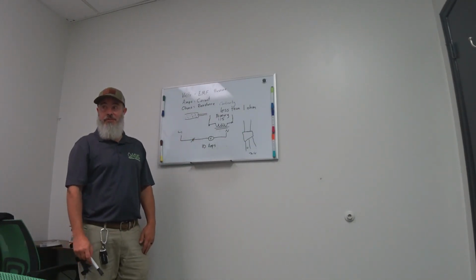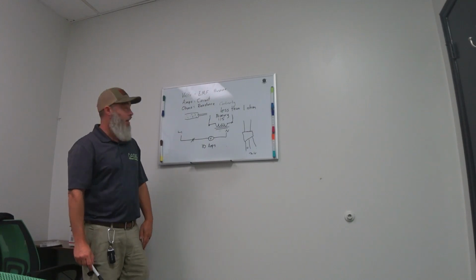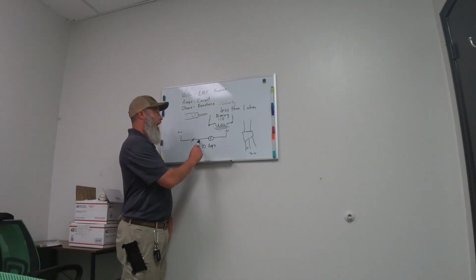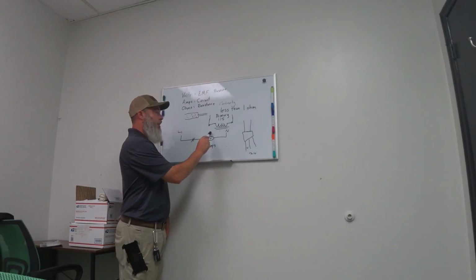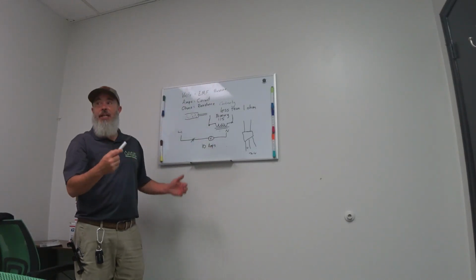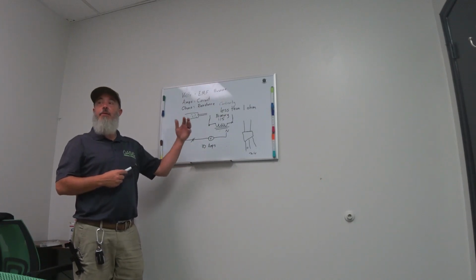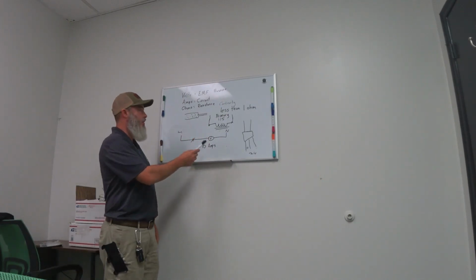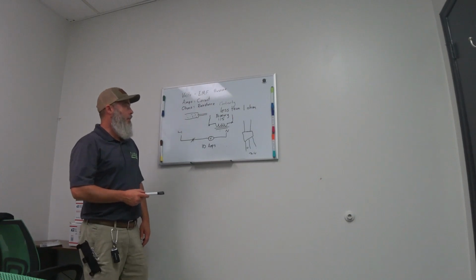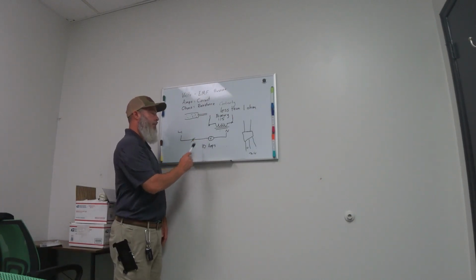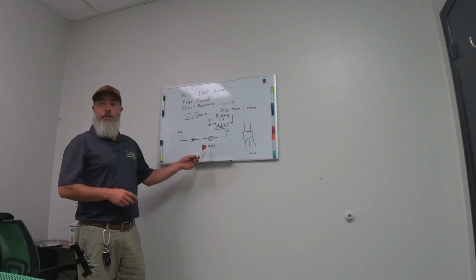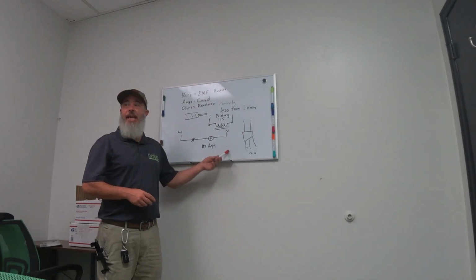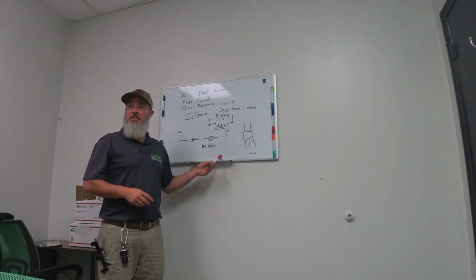and the reason it's drawing 10 amps is the 115 volts and the resistance in this load. Like I said, it's a resistive load, like a light bulb. The higher that resistance in a resistive load, the lower the amps, because the amps can't get through that resistance.